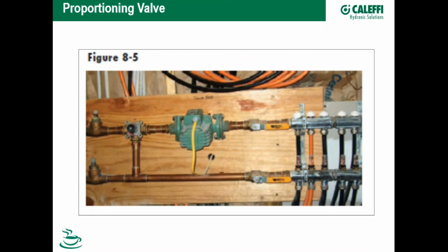And my question always to them is, are you looking to do radiant heating or are you looking to do floor warming? Because the reality is, depending on the design of my radiant system, you don't get a whole lot of floor warming when you're putting out 80 or 82 degree water to that floor.